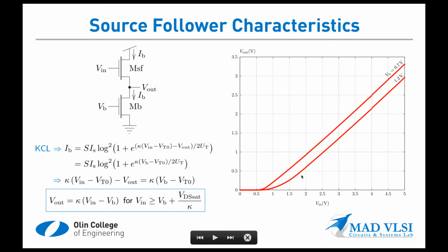And these lines do look relatively straight, although if you were to actually hold a straight edge up to them, you would notice that they are slightly steeper here than they are down here. There's a little bit of positive concavity here, so these curves do actually slightly curve, concave up, and that represents kappa shifting because the depletion layer is increasing in its thickness, and the Cox over Cox plus C depletion therefore is getting closer to 1.